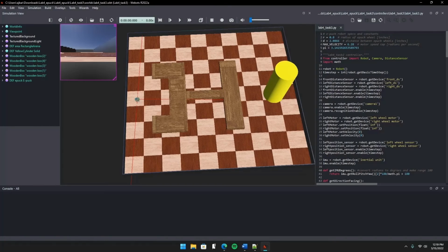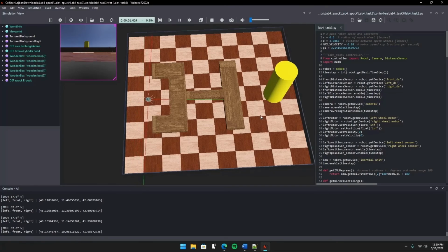I've got like an actual bug in my Task 4 controller that I've been trying to iron out. It's kind of breaking the wall following on specific corners. I tried both wall following left and right, and it kind of breaks at the same points here and here. It'll stop wall following. We call it motion to goal when we're driving straight towards the goal and there's no obstructions. And from what I can tell, the bug I have here is rather than switching from wall following to motion to goal, it's kind of stuck in a loop, wall following and then trying to detect the goal every once in a while.